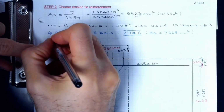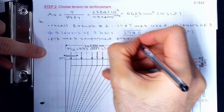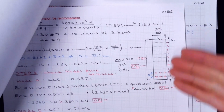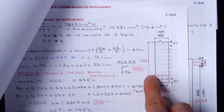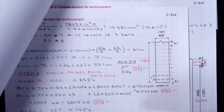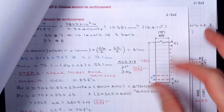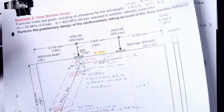So I'm going to say fit was checked previously. So I'm not checking that. If you remember, this was the fit we did. We used 10 layers. No problem. If 10 layers fit, 9 layers would definitely fit. You can spread the spacing in between. Usually reducing it is a problem because you don't want to go less than the minimum. We didn't have any problem with that for this problem. So you can increase it and you can get the centroid at any point. So this is already done, no problem.